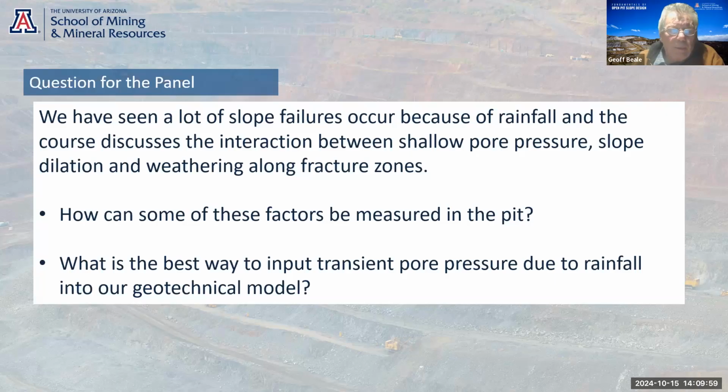And then the other thing is to put in some shallow horizontal piezometers, maybe not so shallow, but horizontal piezometers. Again, these can be drilled slightly downwards, and you put TDRs in with them to measure where the deformation is. So those are the 3 things to measure in the pit.